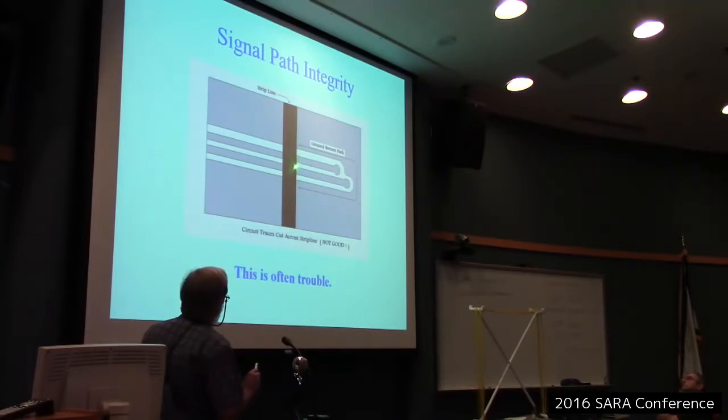And that can actually make a little circuit or structure called the slot antenna. You can take a very large sheet of metal, put a slot in it of the right size, hook a coax across the slot, put it on the side of an airplane, and you have an antenna that sits flat but yet radiates very well.